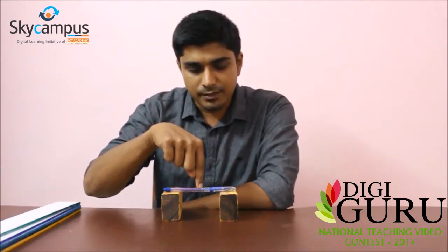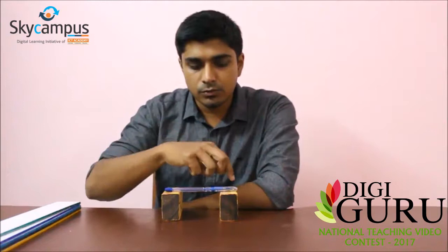In this tutorial, I'm going to be talking to you about beams and the different stresses that develop in the beam when it's loaded. A beam is basically a structural member that transfers any vertical loads to other members of the structure. For example, I have this pen placed in between these two wooden blocks. If I apply a vertical load on this pen, it distributes that load onto these two wooden blocks. So this pen acts as a beam.